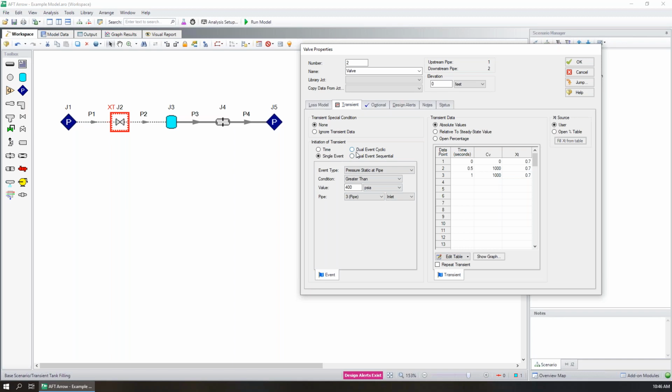And you can also get more complicated where you can have, if the pressure exceeds this amount and the flow rate is below this amount, then open, or trip your pump, or change this control set point. You can really create a whole range of different options that will all be calculated for you, because once you're starting the transient event, you're really letting the system react to whatever change that you've initiated. You're not specifying every change, you're not specifying every result, you're seeing how these things naturally will interact with one another.